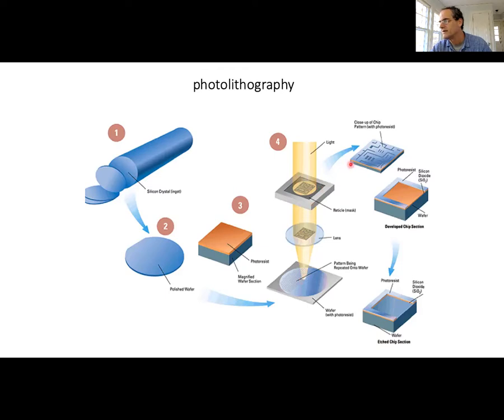Then the wafer can be exposed to a solvent, acetone, and that will remove the photoresist from the areas that we don't want it, leaving behind photoresist in the areas that we do. We'll have transferred our pattern to the surface now. Okay, so we might end up in one little region with something like this.